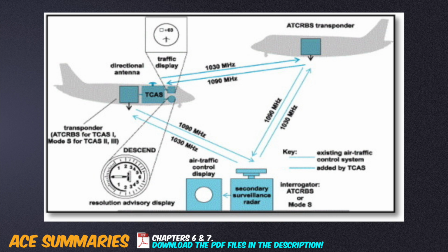Let's talk about avoidance systems. TCAS stands for Traffic Collision Avoidance System. It provides maneuvering information to aircraft with conflicting flight paths. It uses the secondary surveillance radar, aka transponders, and is dependent of ground stations. Correction, it's independent of ground stations.